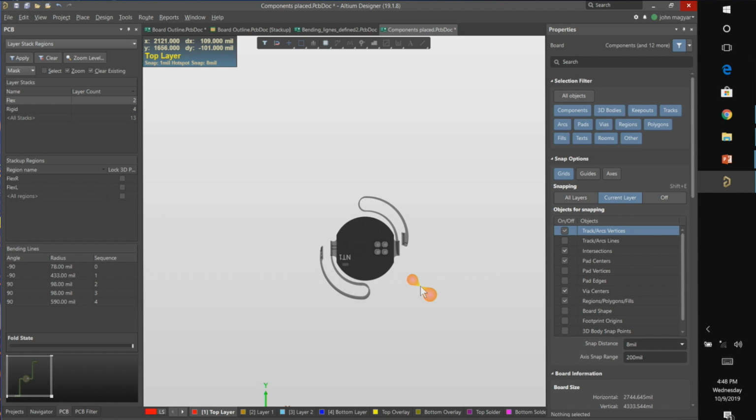Your fabricator would probably have the best guidelines. They're the ones that are responsible for manufacturing it, and they definitely have quite a few rules. We don't yet have design rules specific for flex, but they have general guidelines and documents: holes can only be a certain size, down to a certain limit, and then you have to have a certain ratio of diameter to the hole size.